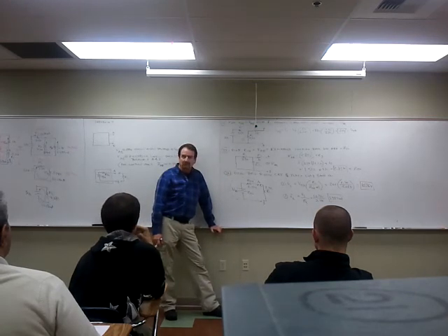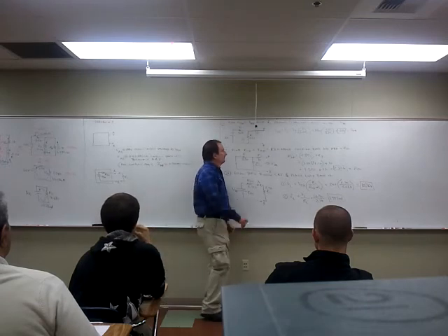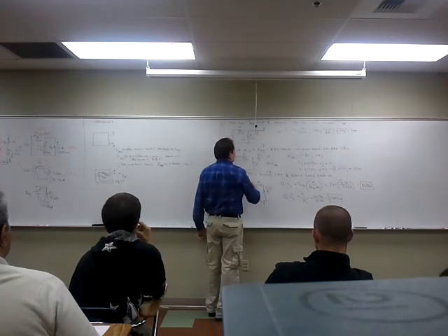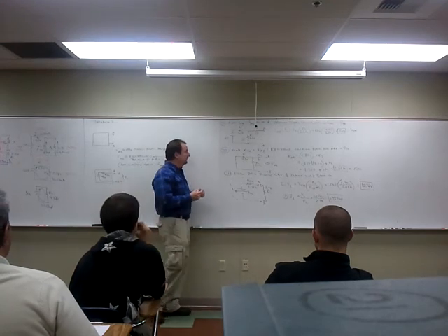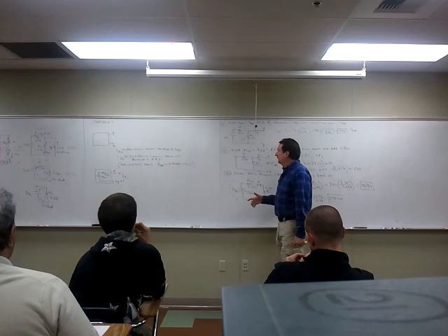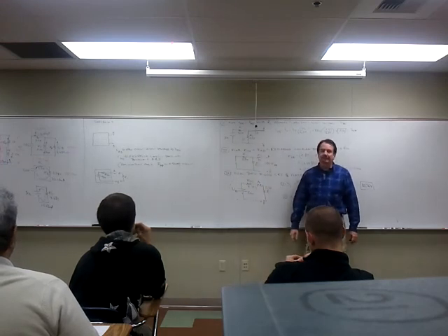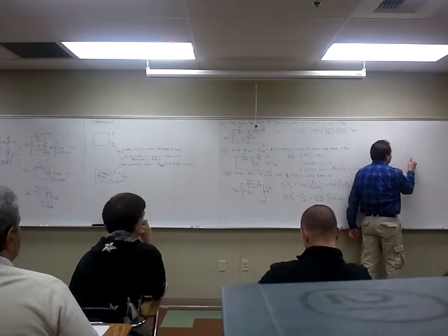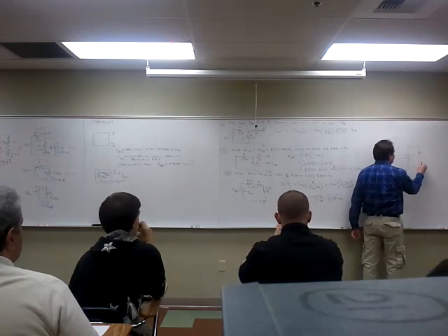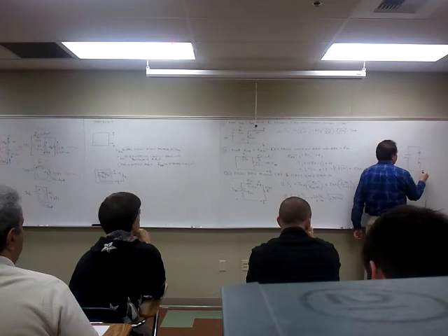Open circuit means no load, no path. So I removed the load. You label the 2 points where you remove the load A and B, just for reference purposes. Now in this case, when I remove the load, resistor 3 is hanging out in free space. If I redrew it like this, effectively this is the circuit.